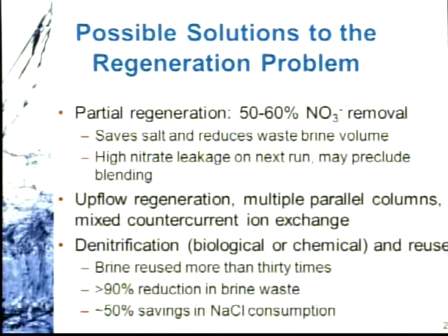Upflow regeneration, as I said before, can help minimize the brine, and we already talked about parallel and countercurrent. Now, another area that's seen a lot of research in the last decade or two, longer than I've been involved in this, includes denitrification of the brine and then reusing it. We heard a lot yesterday about biological denitrification of the primary treatment flow.